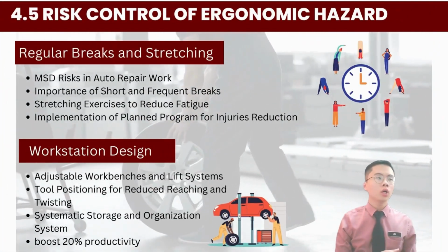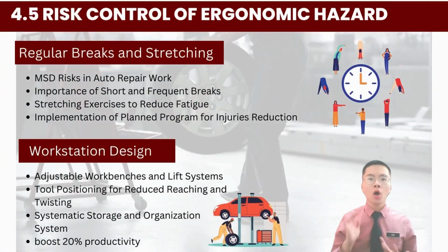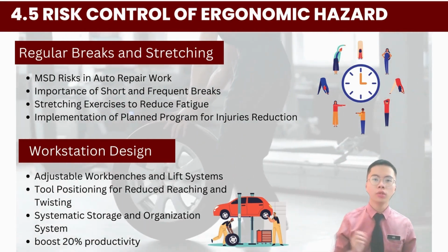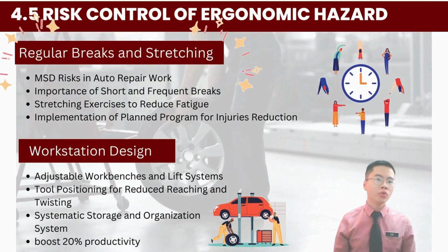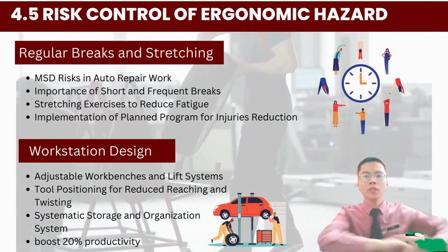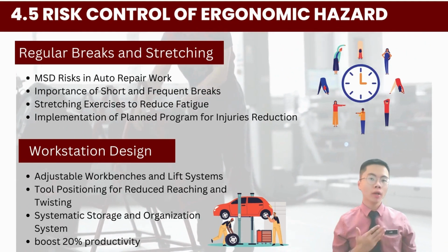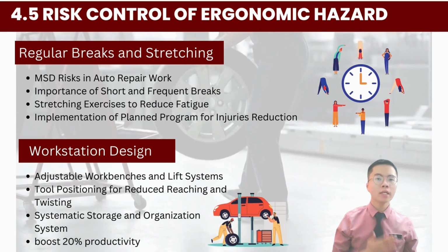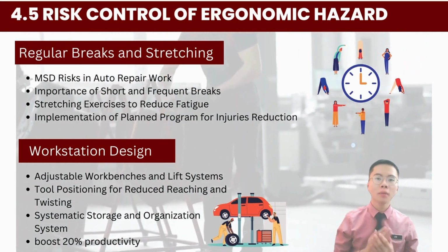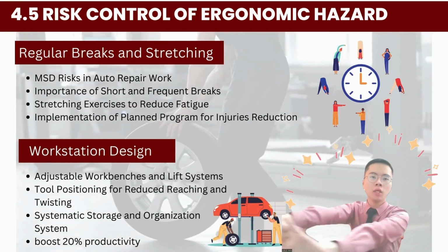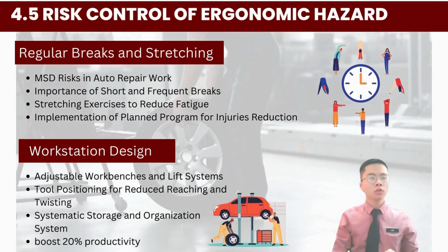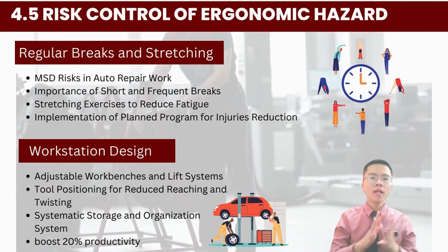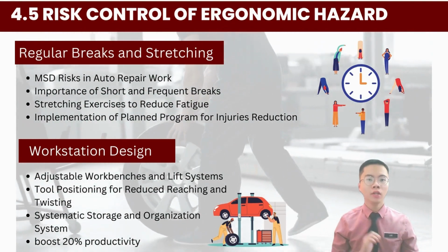Next, moving on, the risk control of the ergonomic hazard. Auto repair workshops often face musculoskeletal disorders, or MSD, due to the nature of their work. To address this, regular breaks and stretching activities are crucial. Short, frequent breaks during the workday reduce fatigue and the risk of MSD. The King Medical Repair Center management and the managers should lead their employees to do some stretching activities every morning before working hours and also every 3 hours during the working day. Implementing such a program can lead to a significant reduction in work-related injuries.